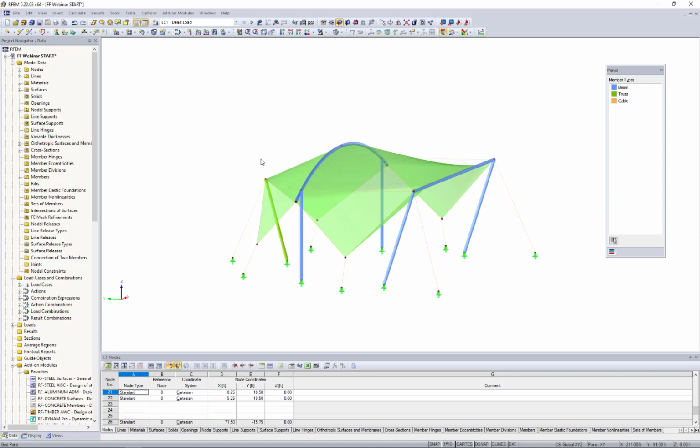This add-on module allows us to define predefined properties such as these pre-stress forces, cable sags, and so on, and it will find the deformed mesh for us before we continue on with the static analysis. A simple way to explain this is the cable elements are completely straight. Form finding will allow us to define a cable sag, for example. We run the form finding process, and then the program will come up with the catenary shape for us.